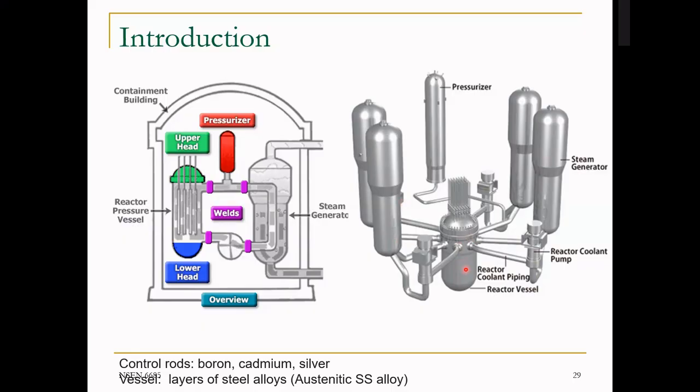So the reactor vessel, which is this, a pump is here, a steam generator, and there is one pressurizer that's serving the 4 loops. So this is called 4 steam generator loops. And you will see that the hot fluid comes from the top. So there is hot fluid coming out. We call that the hot leg, right?